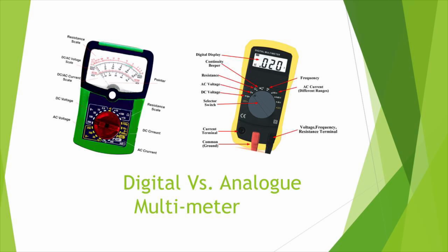Although analog to digital converters can be very fast, your eye cannot keep up with the rate at which the LCD display is updated. For this reason, there is a trade-off between sample rate and display rate, which usually slows down to a few readings per second. I believe now you know both what a digital meter and an analog multimeter are.